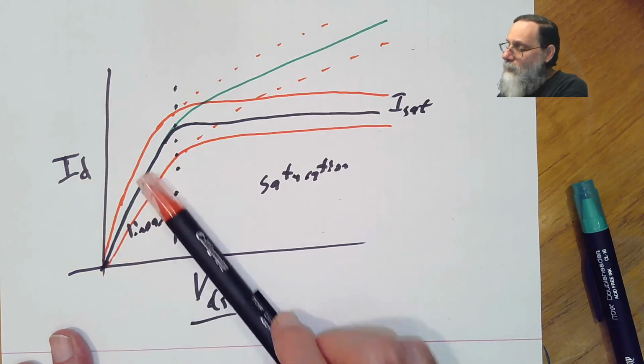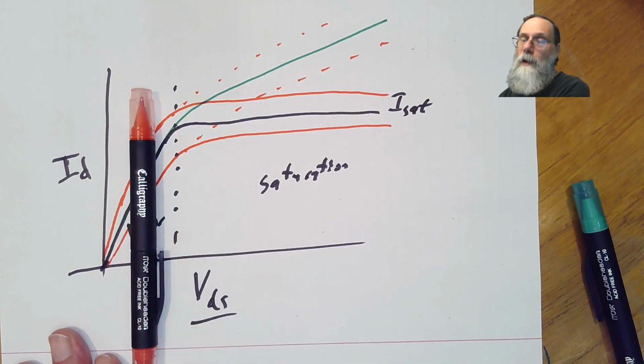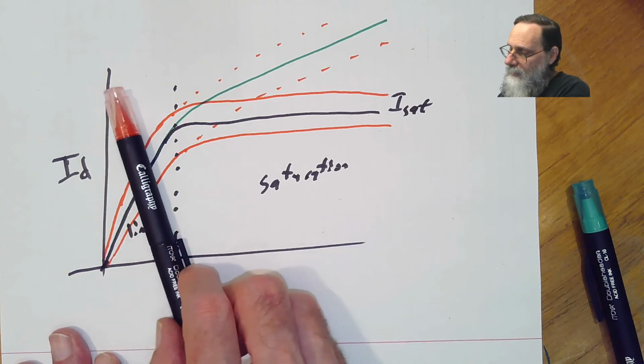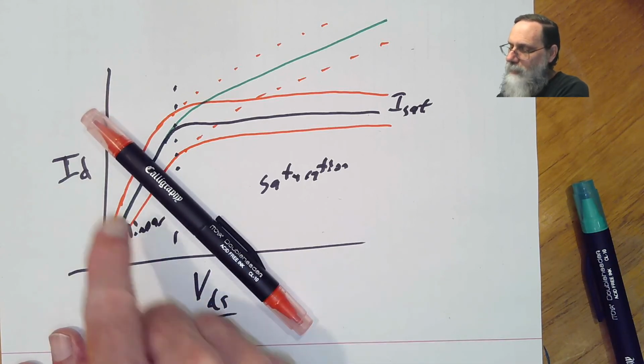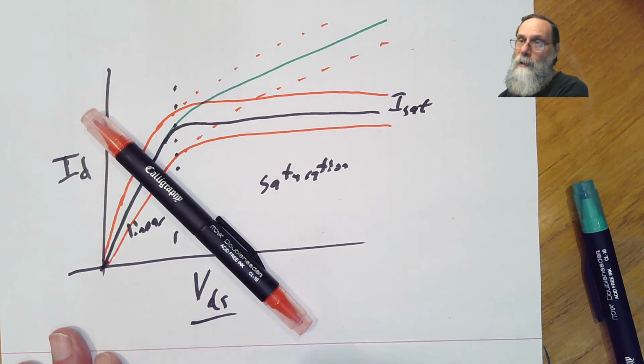If you're in the linear region, things will work fine if you're looking at a transimpedance amplifier where you're holding a constant drain to source voltage. Things look a little bit messier if you've got a load line, because now you're getting quite different operating characteristics, different responses of current to gate to source voltage at different points on the curve.